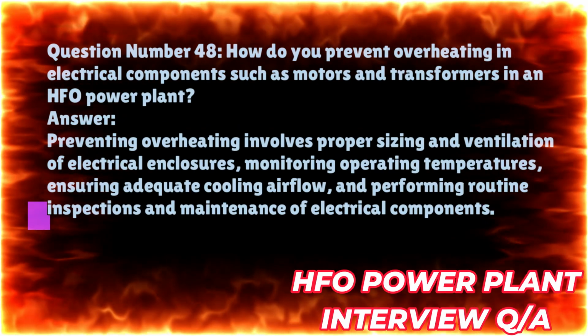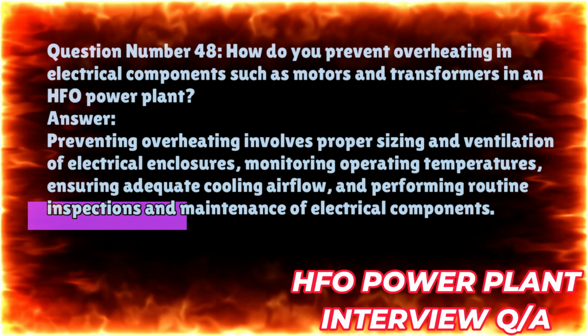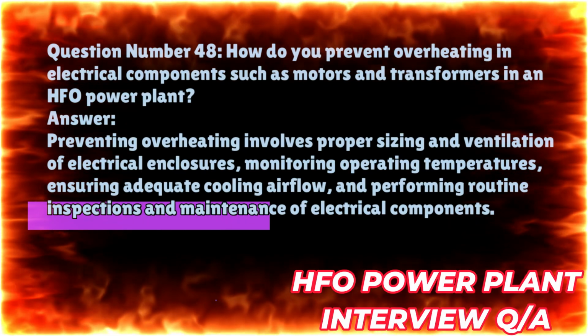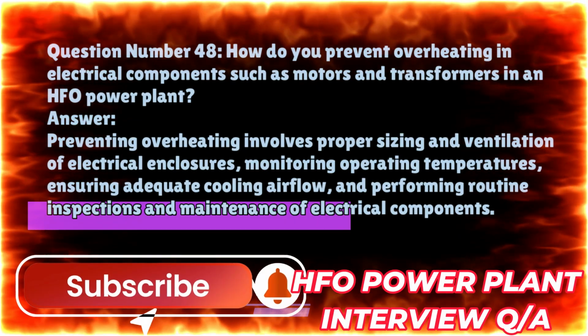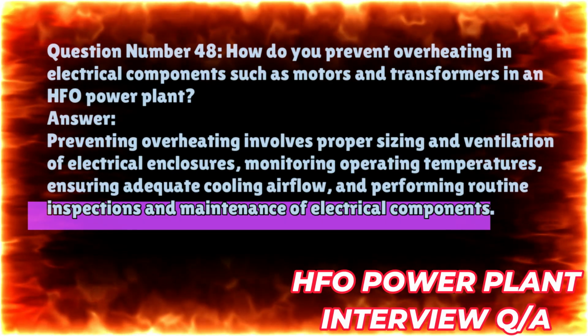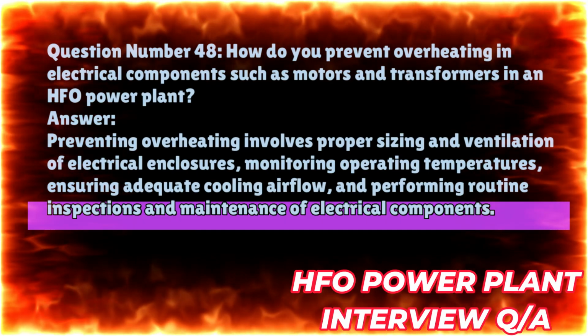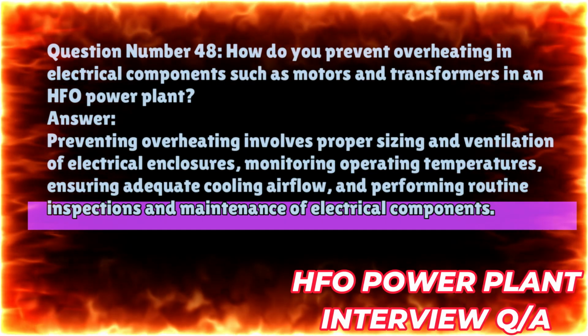Question number 48. How do you prevent overheating in electrical components such as motors and transformers in an HFO power plant? Answer. Preventing overheating involves proper sizing and ventilation of electrical enclosures, monitoring operating temperatures, ensuring adequate cooling airflow, and performing routine inspections and maintenance of electrical components.